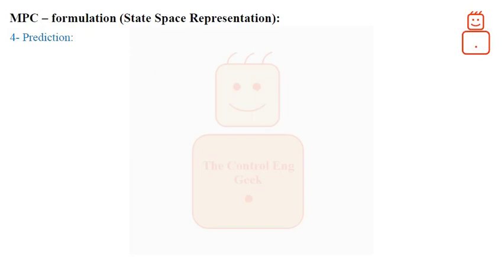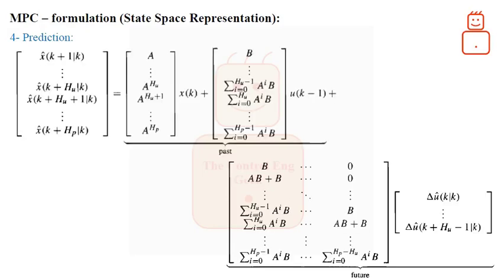It is important to state the following. As we have the prediction expression, we are dealing with A to the power i, as indicated by the red boxes. The power i can have a quite large value. This can lead to numerical problems, especially when the plant is unstable. Thus, the safest way to predict the states for long horizons is, probably, to iterate one step at a time.